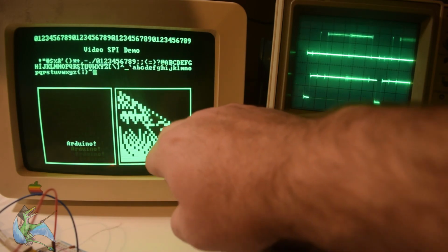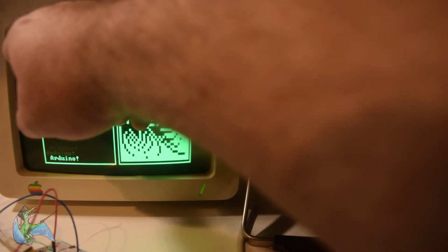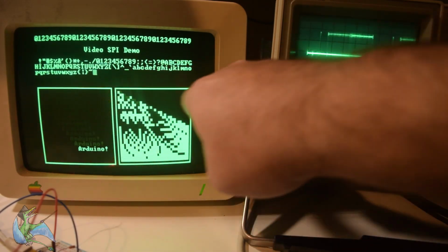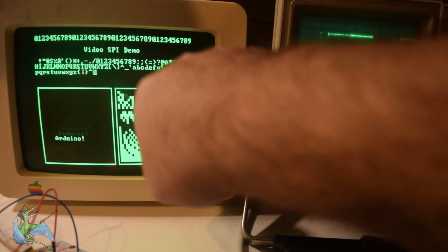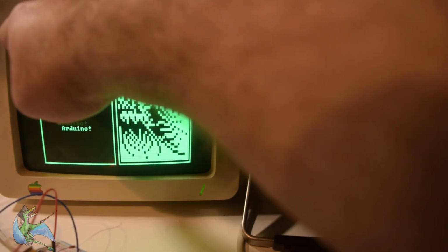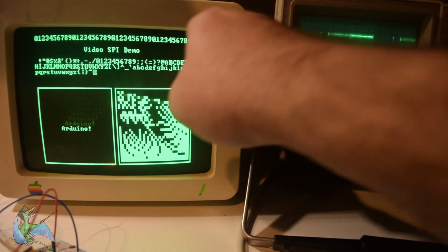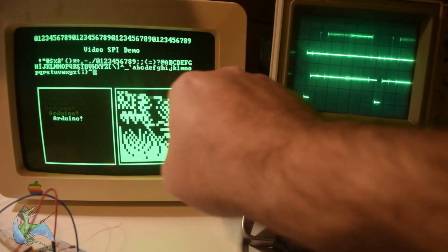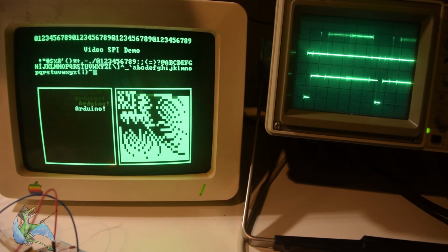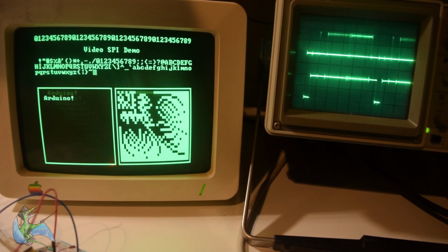Then for 3 line periods, the electron beam will be back in transit back up to the top, and then essentially you start counting at 4 again. It starts painting across. So that, in its most basic sense, is how you can do NTSC video.